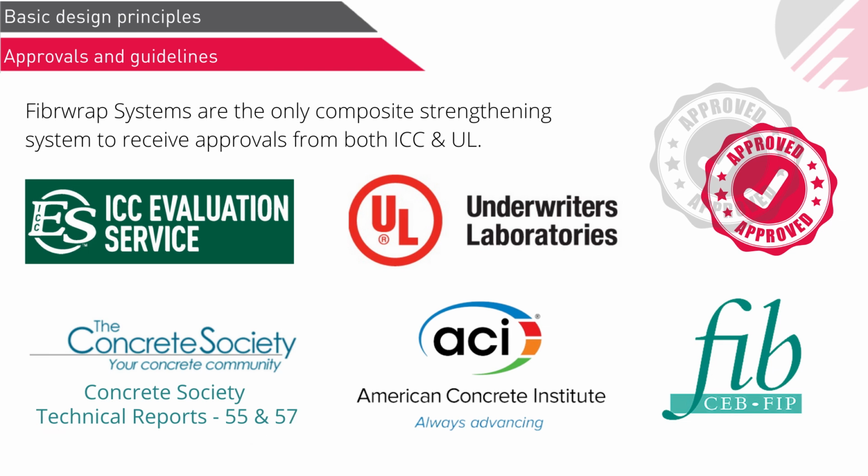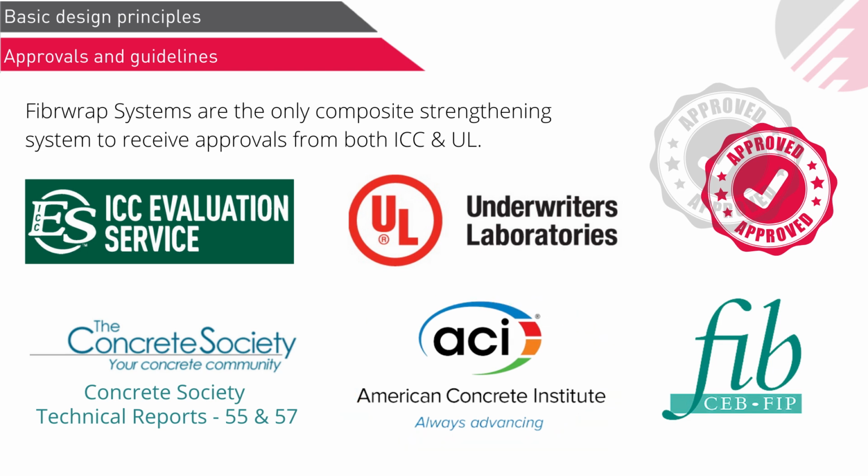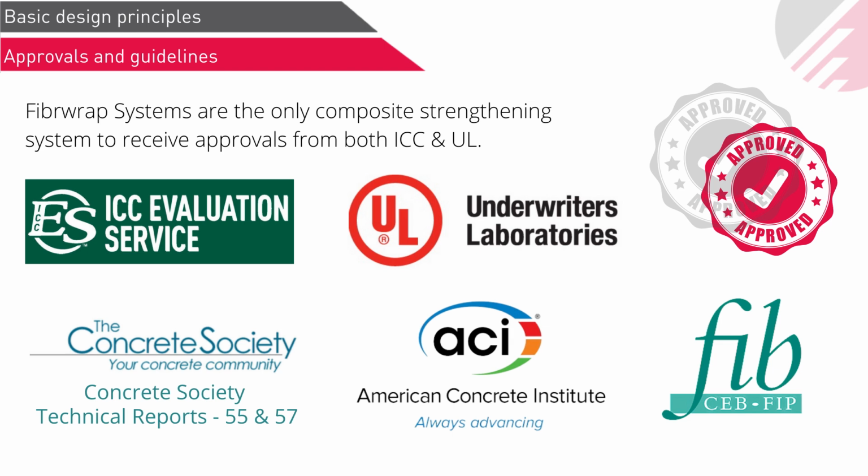TR57 gives you guidelines in terms of application and testing, that is, how it should be applied, and maintenance and testing requirements. Okay. Then there is also ACI 440, which is the American Concrete Institute document. That is also a design guideline, majorly followed in America, but even people here follow ACI, even to cross-check their designs. Then we have FIB 14, which is followed in the rest of Europe. So these are the three main design guidelines which are used worldwide to design FRP.